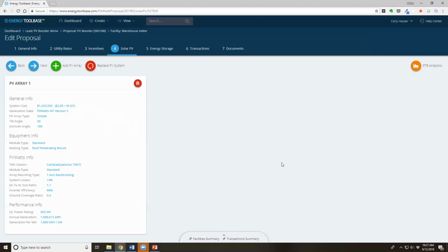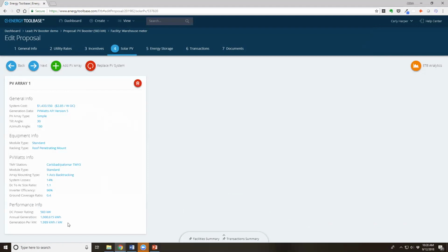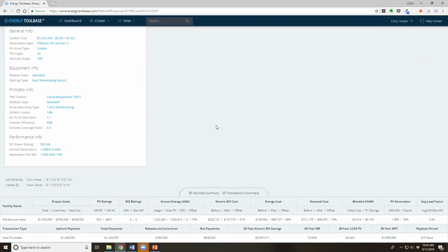Okay, so let's interpret our high-level results here. On the yield side, we're all the way up to almost 2,000 kilowatt hours per kilowatt of yield, translating to over 1 million kilowatt hours of year one solar production. And on the savings side of the equation, let's do a really quick reference down here in the dashboard and see what the value of solar is worth. We're coming in at about 14.5 cents per kilowatt hour compared to 12.8 cents on the fixed tilt system.